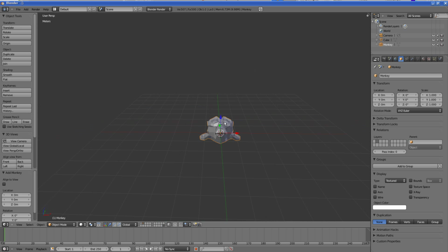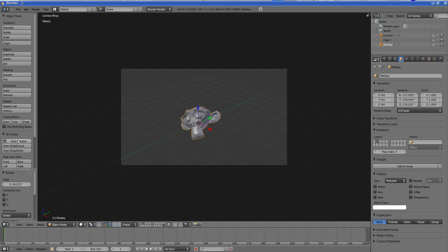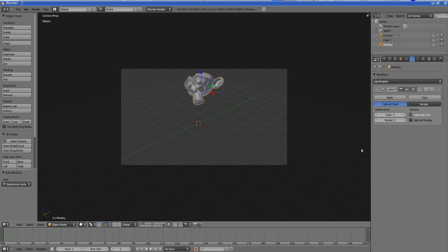Now if I select the object and press R, the rotation is happening around the virtual camera Z axis. If I press R and then press R again, the rotation is in a trackball mode. So let me switch to the camera and then press R twice, and let Suzanne point this way. I'll move it up like this. Apply a subdivision surface modifier and smooth it out.